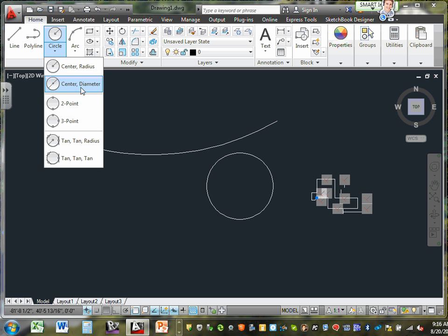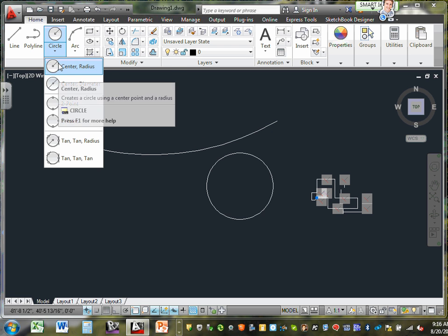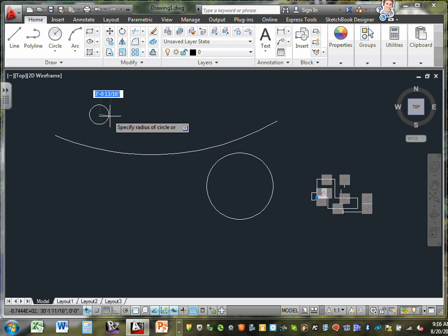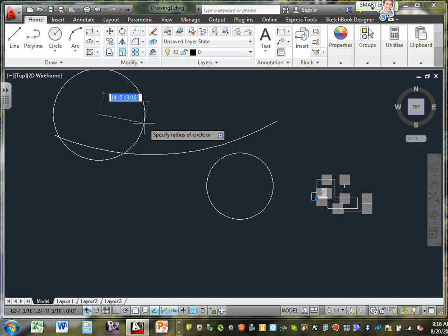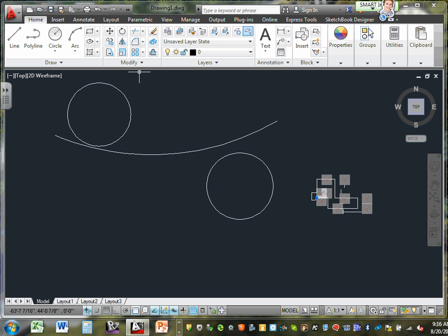Can you guys see it? You can have diameter, you can have radius. I believe your default would be a radius. So can you guys see that when you put 10 here, if you don't put any units next to it, what's the default? If I put just 10, no units, what's my default? Inches. You default to inches. If you want it in feet, you have to put the symbol for the feet right here. Can you see that? And enter. So radius of 10 feet.